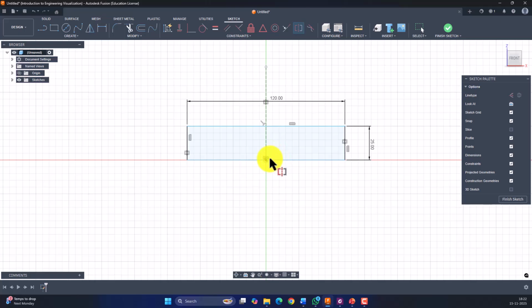Now let's make sure from the origin it should be this one. Otherwise you can fix this coincident with the origin. So this line can be coincident with the origin. Any one constraint should be with respect to the origin. So let me apply a coincident constraint between the origin and this line. Now it becomes black color, which represents that the entire sketch is a fully constrained sketch.